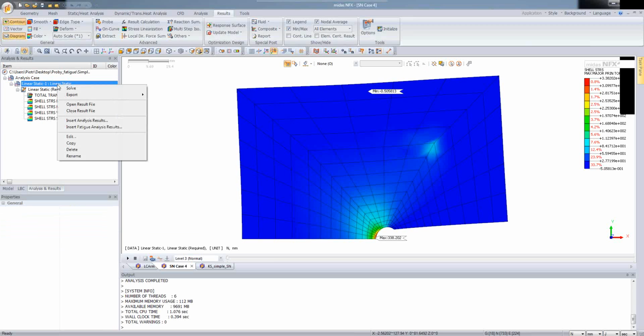And every time before we start doing these calculations, we have to make some decisions related to the process. For example, for the stress life, we're supposed to investigate the loading type, mean stress effects, multi-axial stress correction, and for example, the fatigue modification factor, which is also known as fatigue concentration factor. So these are some points which are related to the stress life method.